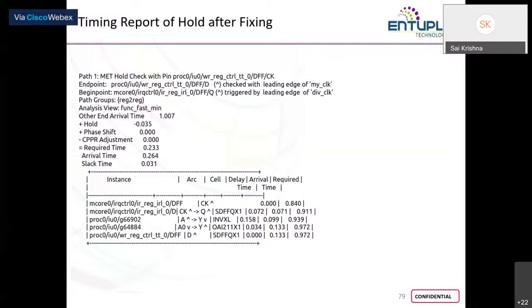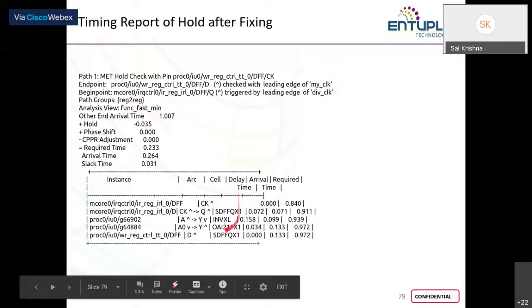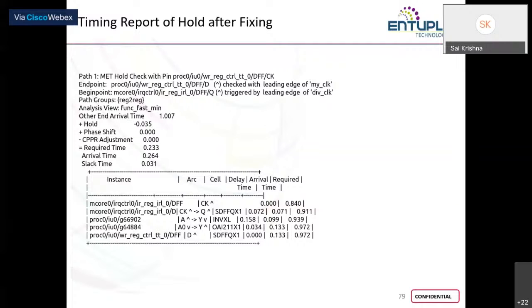Okay, so it is the engineer's responsibility. It is a physical design engineer's responsibility to actually debug the issue. I mean, go through the table, identify the highest delay point, or keep it simple, the point where the timing problem arises, and then take the necessary step accordingly.